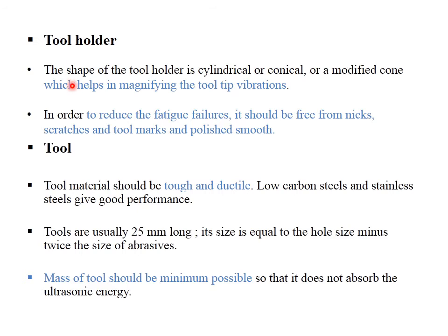Also, the tool holder comes with magnifying tool tip vibrations. So you may see in some of the ultrasonic equipment they come with a booster. So what is the role of the booster in a holder? To boost the vibrations at the tool tip.